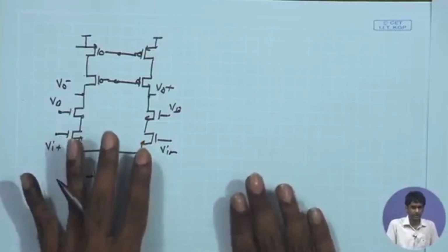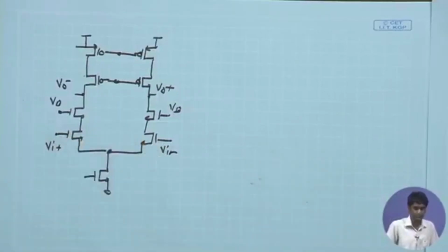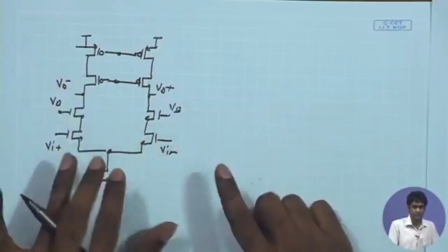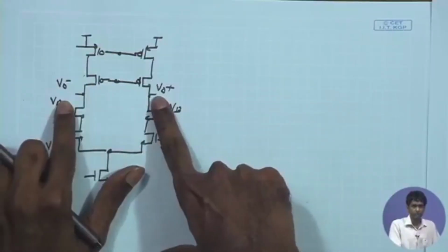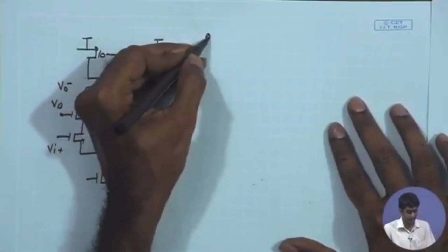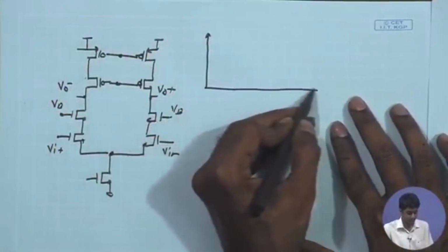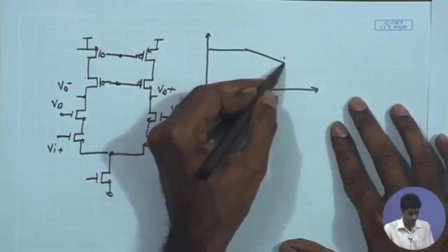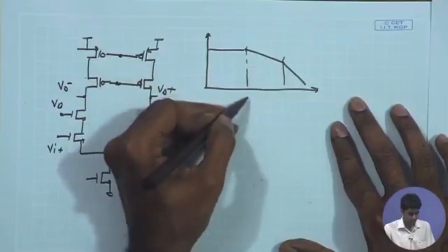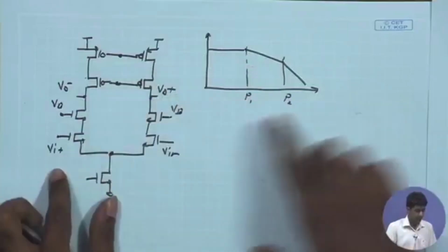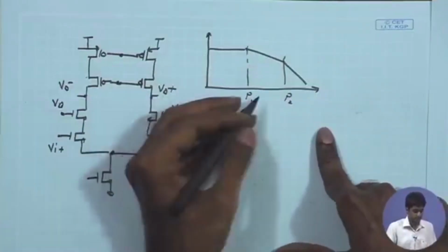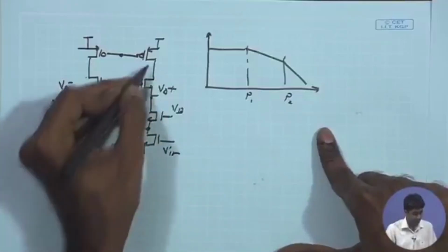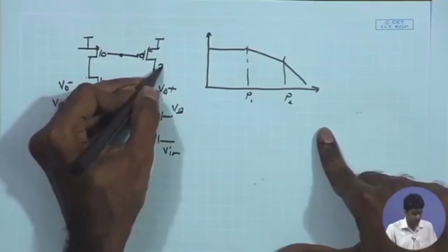So here we have the dominant pole compensation coming into picture. So here we are not going to rely on Miller capacitance, we are not going to use Miller compensation, but going for dominant pole compensation. So you are having the first pole P1 and the second pole P2, where I already have, say, without any compensation, the P1 coming over here and the 2 P2 poles here, and I can call this also P2.